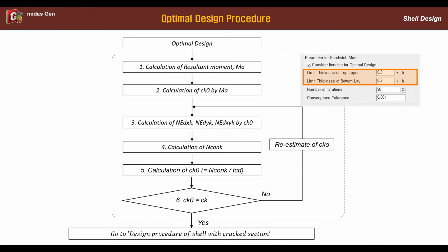However, if it is assumed to be thicker than the membrane force requires, the distance between the layer centers is shortened, and the required amount of rebar increases. On the other hand, if it is assumed to be thin, it may not secure safety, because the allowable value cannot be satisfied when examining the stress of the concrete.